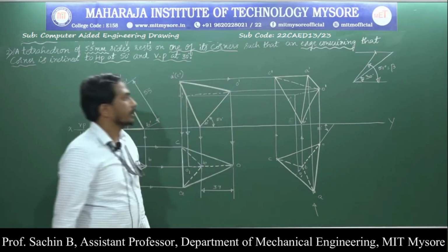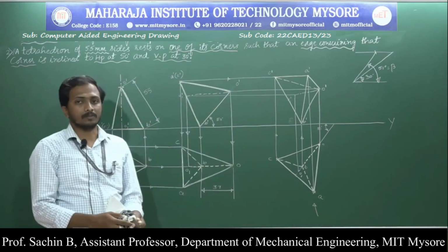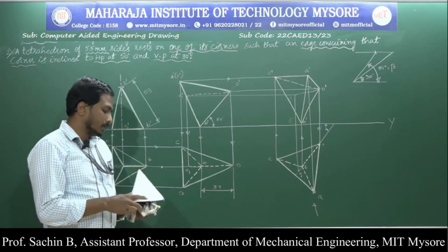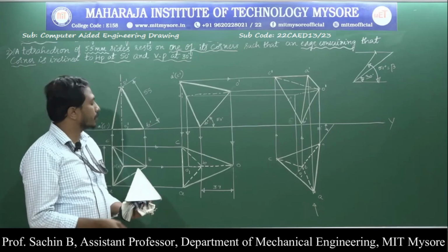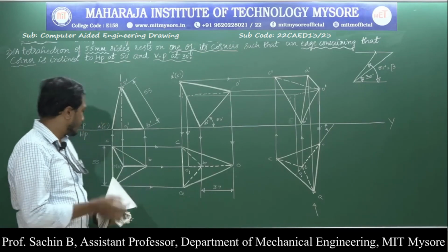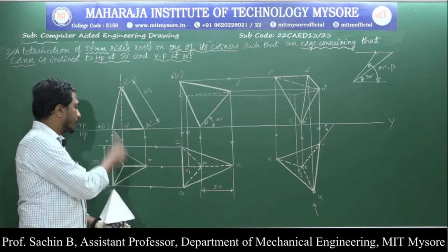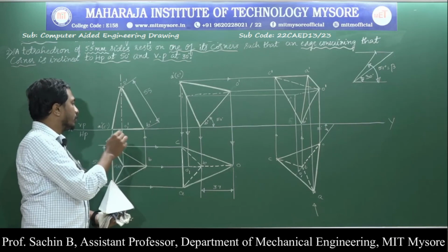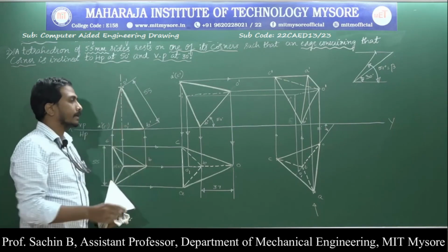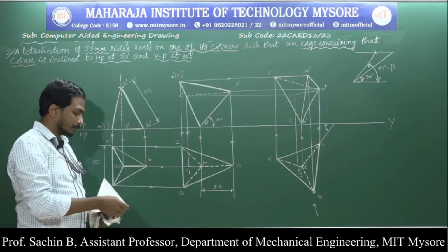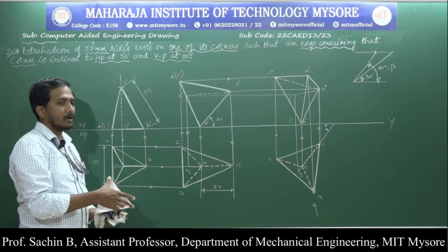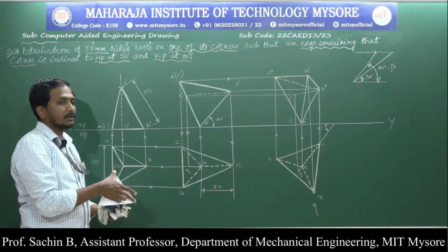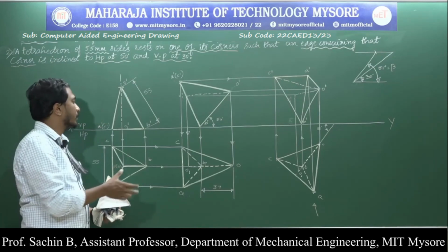Okay, this is my last position of the object when it comes to the tetrahedron. In the tetrahedron, they are going to give a length of 55 mm. Don't get confused: construct an equilateral triangle with 55 mm length. Next, go for drawing the front view. While drawing the front view, first extend the axis, but according to the concept and according to the view of the object, this slant edge, if I project it, is the only slant edge where the required length is available.